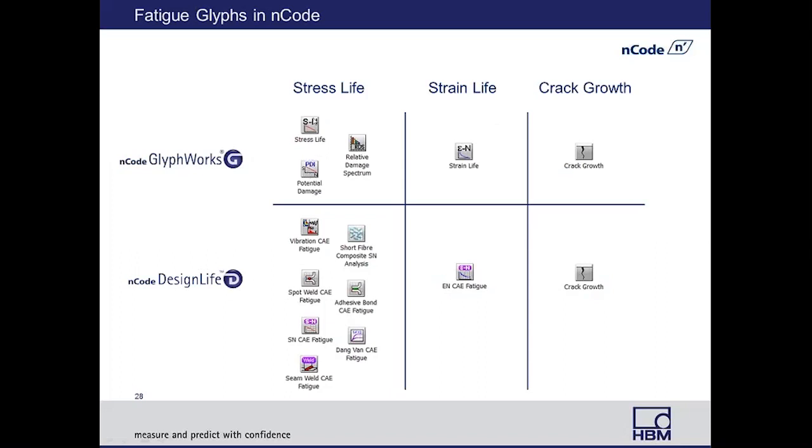The other 2 are going to be relative life calculations. They will be stress-based though. We have a strain life glyph as well in GlyphWorks, and we have a crack growth glyph here. On the design life side of things, we have quite a few different stress life glyphs. The basic one is this SNCAE fatigue.